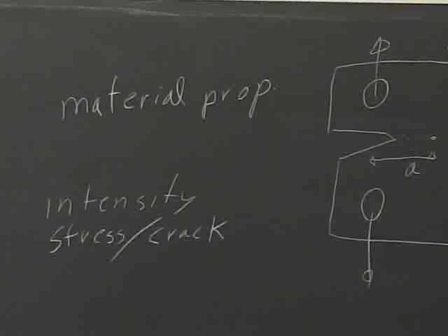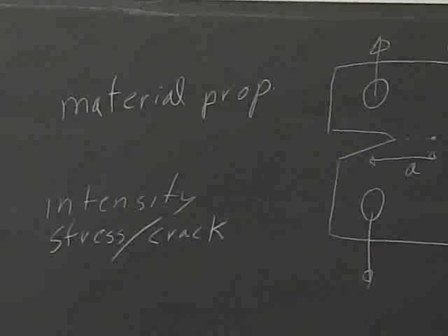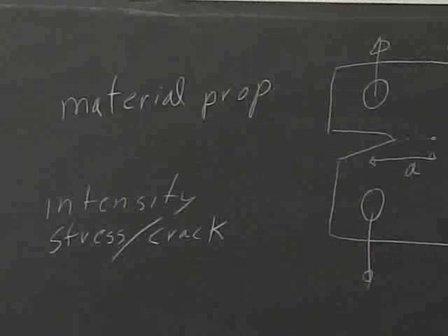One way is to use the inspection technique. So when I was working at Bombardier, if we were going to do a liquid penetrant test, for example, on all the aircraft components, we'd evaluate what's the biggest flaw that the inspector may miss, and use that as the starting point for the life of the part. But the only way in practice we were able to do it was by redundancy.